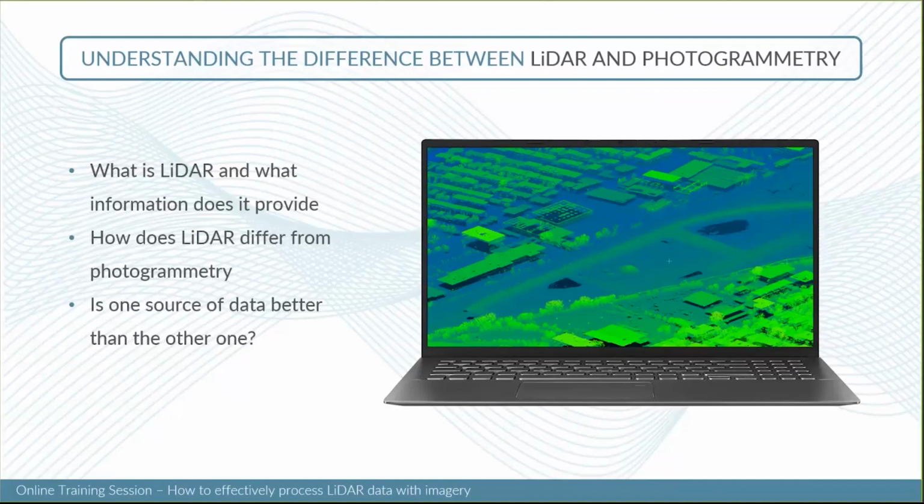The main disadvantages is, on certain areas, you cannot map under elements such as trees. So if you want to measure the height of your canopy in dense forest, photogrammetry is not well suited because you will basically have the top of your canopy. You maybe need to have LiDAR to have the area under your canopy.